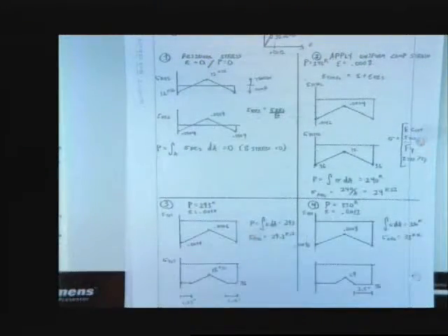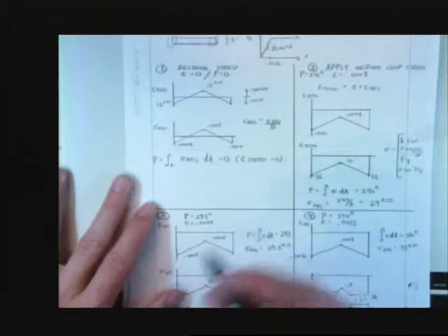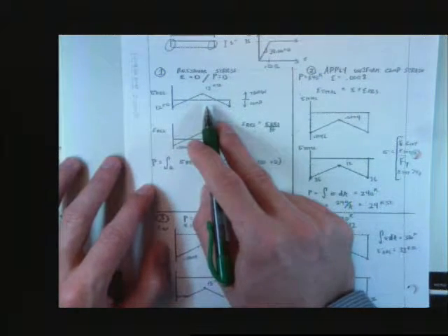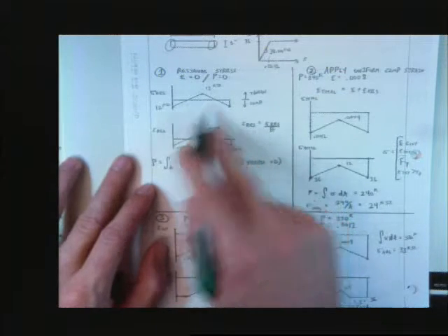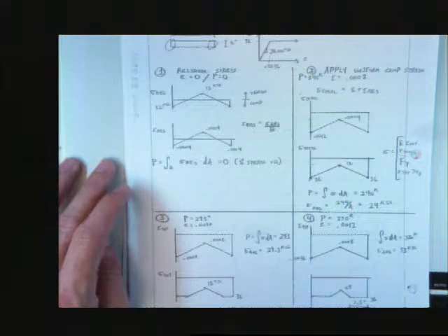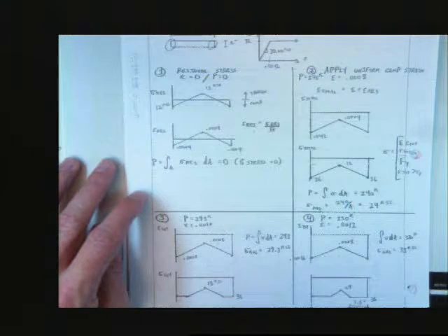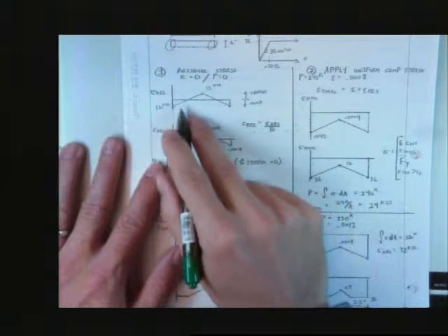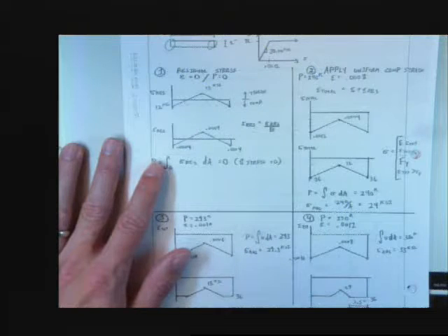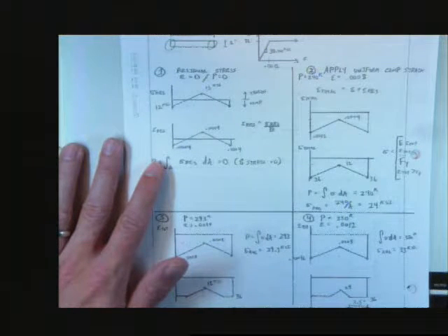So under no load whatsoever, and this, believe it or not, happens in every single piece of steel on the earth. The only way you could make this not happen is if you took it all up to the same temperature and you cooled it ever so slowly. So every single ounce of steel experienced the exact temperature, and you brought it down very carefully over days. Doesn't sound very practical, does it?